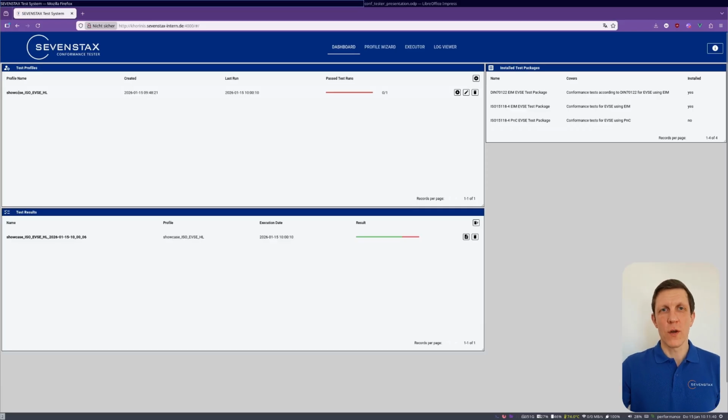But all theory is gray, so let's dive into a quick demo of our testing application. For this demo, I am running the conformance tester against a system under test that is simulated by software locally rather than an actual hardware EVCC or SECC. To do this, I am using a virtual Ethernet interface instead of the PLC modem, but I will get into this feature in a moment.